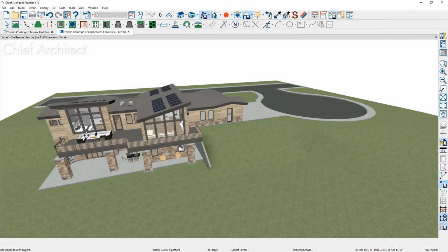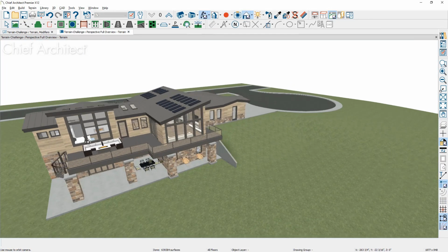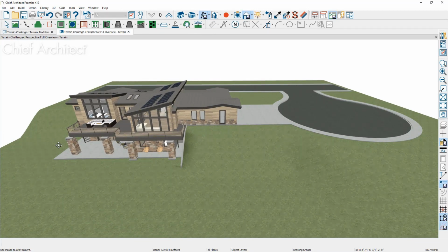And back in the 3D view you can see that there is actually no change at all because we made the changes in all of the elevation information. If you plan to use sea level elevation information, do that at the beginning when you create your terrain perimeter, and then all subsequent elevation data will use that as the basis.